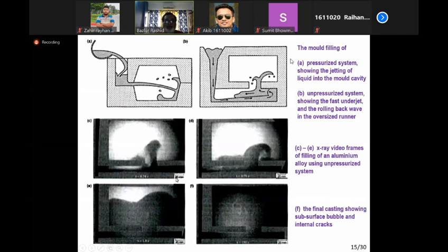There is another example. So this is the screw. It's a thin screw base, and it is a runner. Liquid metal is flowing, hits the far end wall, rolls back, and then goes up into the mold cavity. There is a fountaining effect, not much, and then it rolls back again and starts filling the mold cavity. Not much fountaining now.